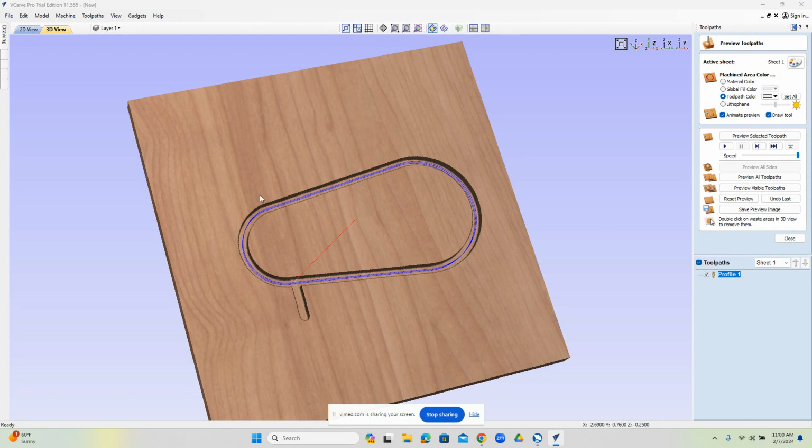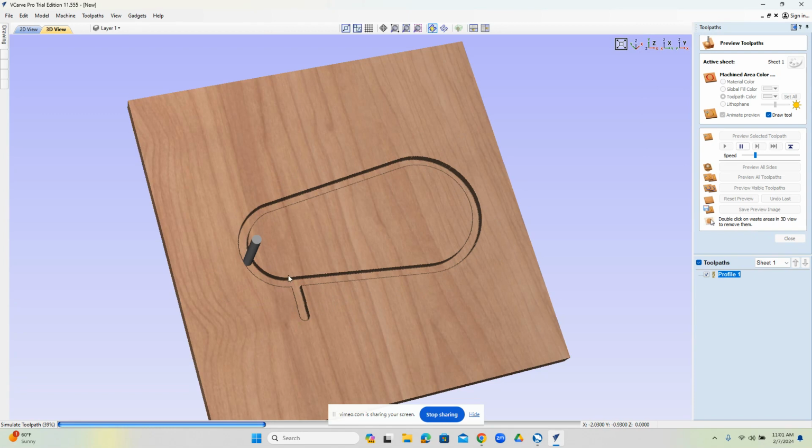I don't know why it's burning there and nowhere else. It's, I guess, when the tool is coming under full pressure, you could change direction of cut and stuff like that to make it less. If you conventional cut, there's less tool pressure versus climb cutting. So if we went counterclockwise on this shape, then that would be like, this is going clockwise, it appears, right? So that's a climb mill. So it's a very aggressive entry into the cutter. The cutter takes a big bite to begin with. If we reverse this direction, then that in itself may just solve the problem.